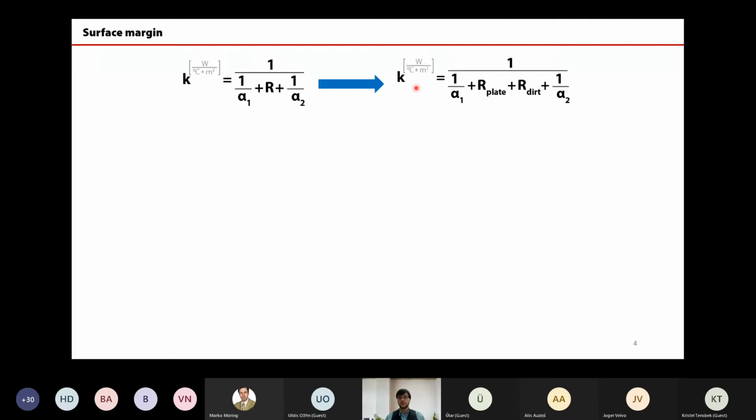And you can clearly see that if we add more members to the equation in this bottom part, our heat transfer coefficient is going down. What it means for my load is that it needs to go down if all the remaining parameters are kept the same. In other words, the heat capacity, or amount of heat, will go down. That means our user will not receive as much heat as he wants or needs. How can we compensate for it?